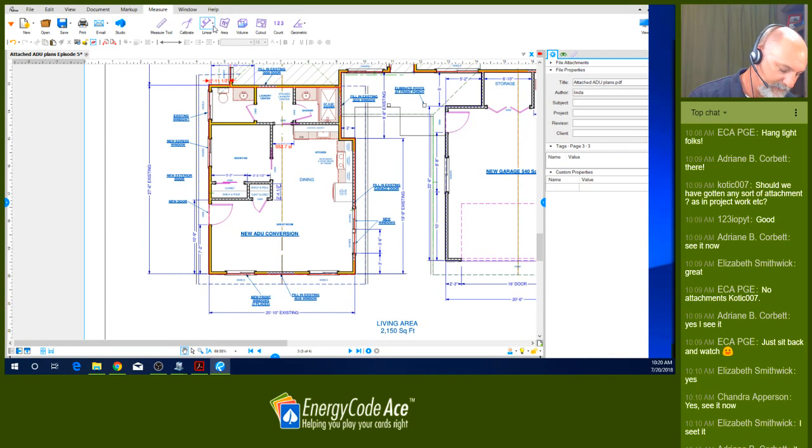So we've got 27.5 on the left, 20.83 on the front, 27.2 on the right, and we got 5 feet on the back. I got about 80.5 feet linear footage of slab edge. So that should wrap up all of our takeoffs.